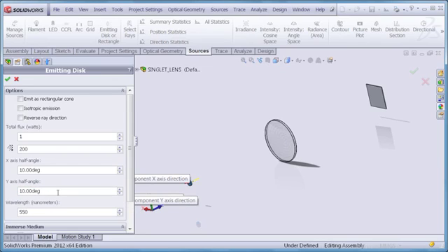If I want to define a collimated beam, I merely set both of these entries to 0. In that case, all of the rays will have the same direction, but they will be randomly distributed across the surface of the emitting source.